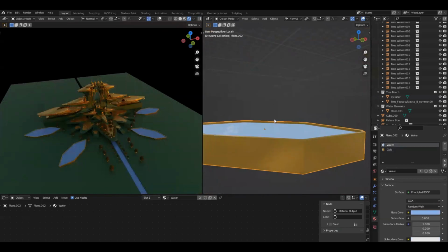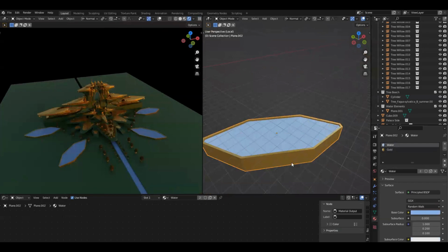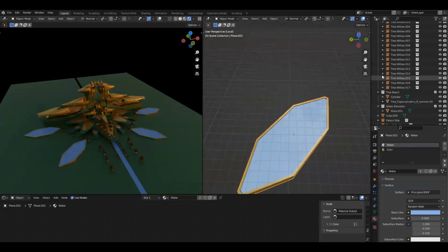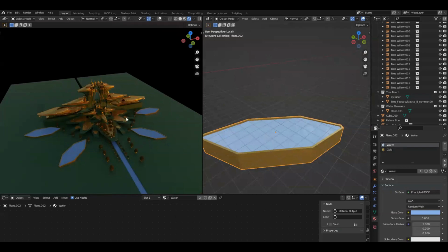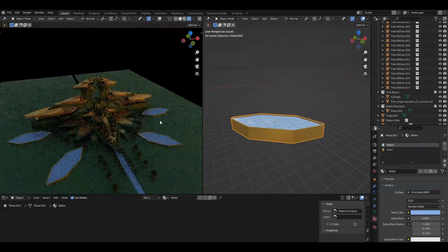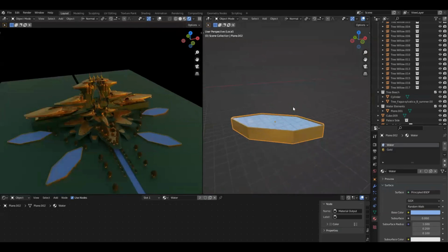And I did that in edit mode instead of adding in a new object, by the way, just so that it would place automatically in all of these linked objects and instances. Because if we had just made a new object for that, we'd have to manually place it in all these spots again. So yeah, same kind of trick we're doing with the human actually, where we're linking everything so that if we need to change the scale later, we just do that in edit mode.